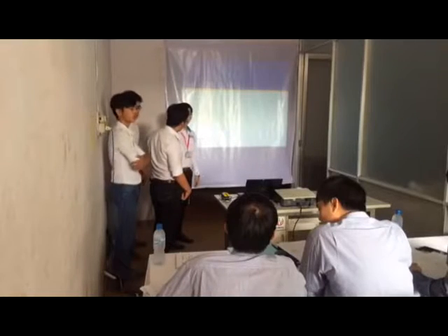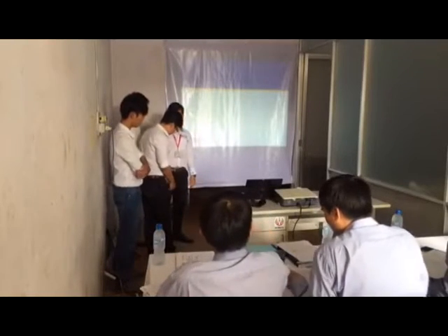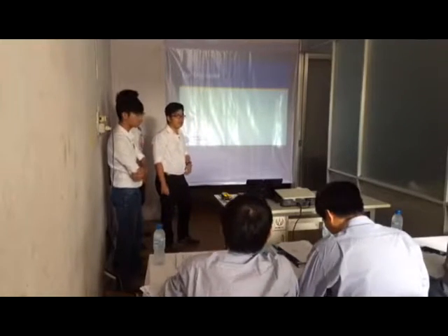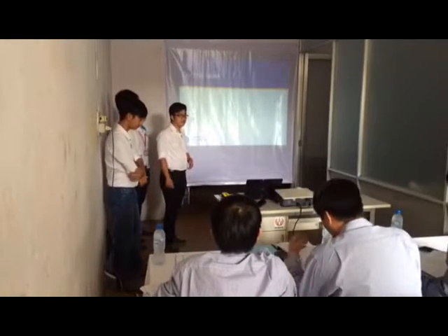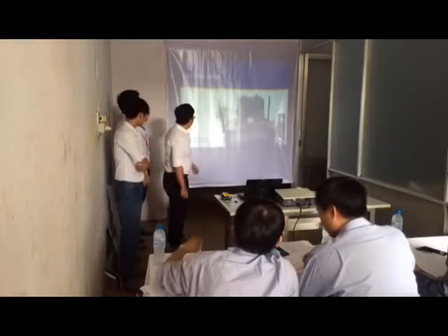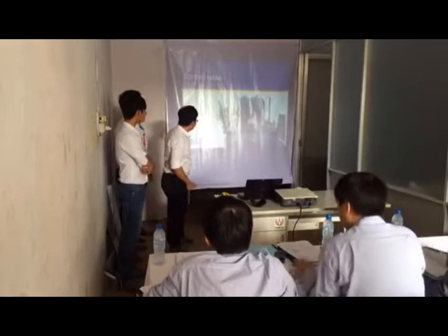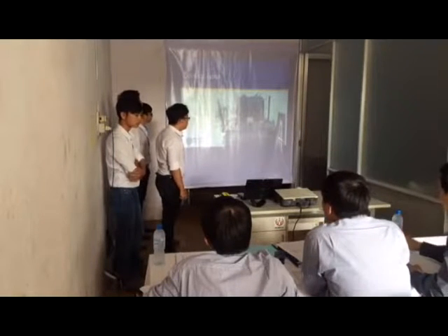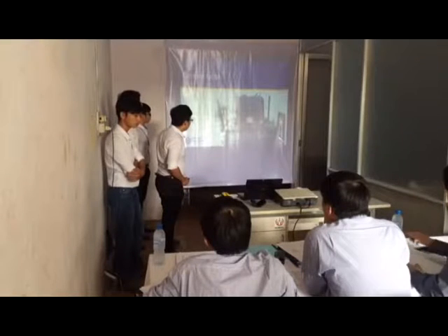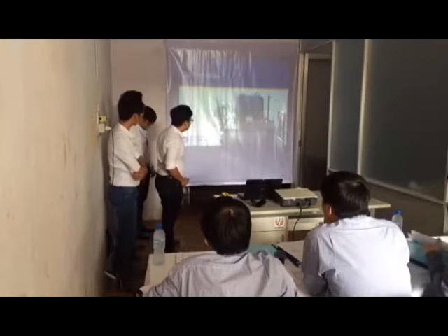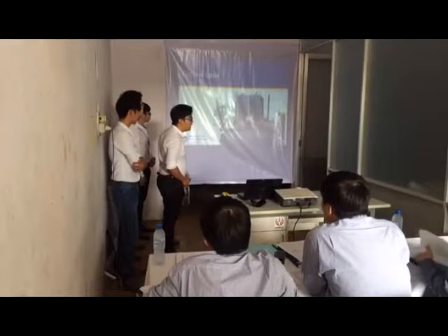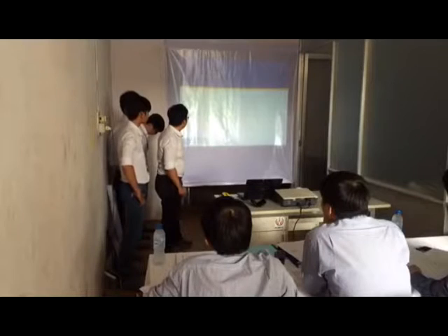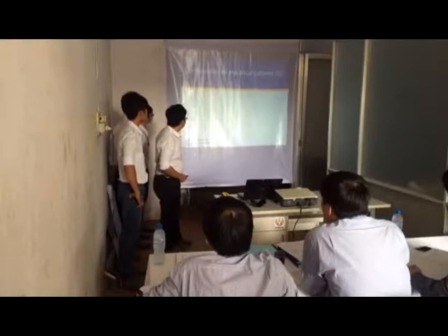And then Mr. Hùng will continue the presentation. The control component helps the user interact directly with the control system. In our control table, we have 3 switches. Number 1 is used to turn on or reset the electrical cabinet. Number 2 is the emergency stop, and we use number 3 to turn on or turn off the welding gun in case of a breakdown or problem. Now I will show you our electrical cabinet.